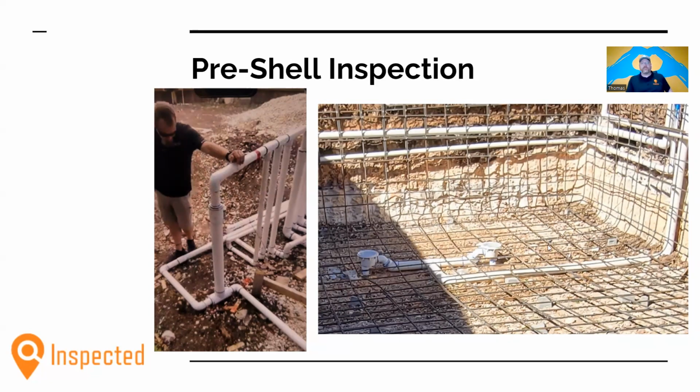Additionally, there is a structural component to consider when you're installing larger pipe. In this case, the pool floor has some gravel on top of it, and then the pipe is on top of it. It's a 3-inch pipe, and sitting on top of that pipe is your reinforcing rebar, and then on top of that, it's probably about 3 inches of concrete, and that is not a significant amount of concrete for a pool shell, especially of this size in these conditions. So when you are considering larger pipe options, discuss with your structures professional on whether you should put a trench underneath, opt for a single main drain, go on the sidewall suction, or other options that are available, including eliminating